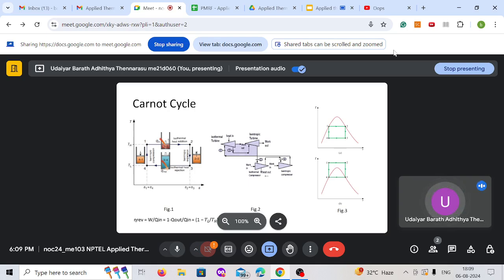So how do we overcome this? The other way of overcoming is this. As I told, we can go from an isothermal to an isobaric process. We can convert it to an isobaric process, and again, we have to avoid this wet region or a two-phase flow. So we shift this Carnot cycle at the top, such that 3 to 4 is in a saturated state. So this is one kind of arrangement you can have. The easier way, it's again a gas power cycle.